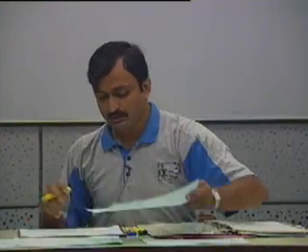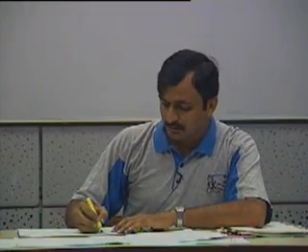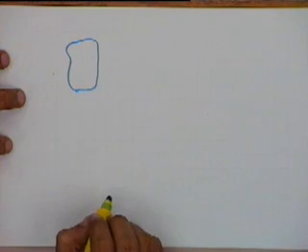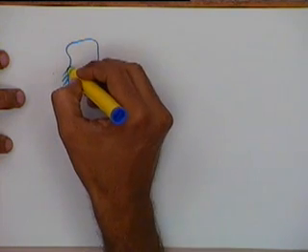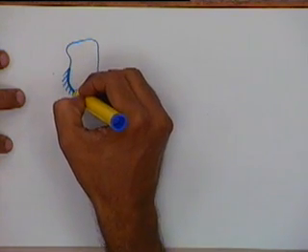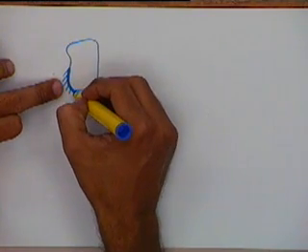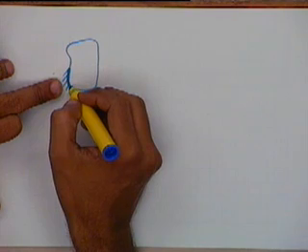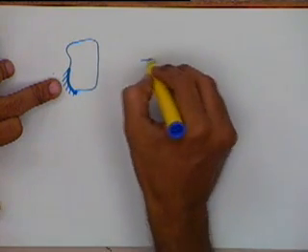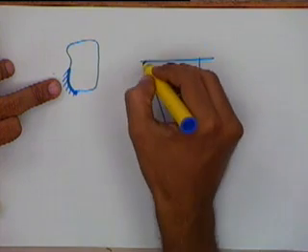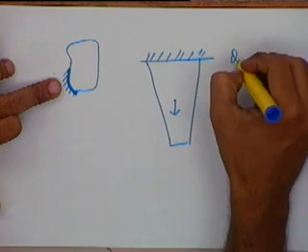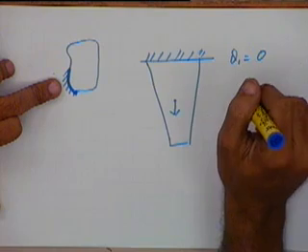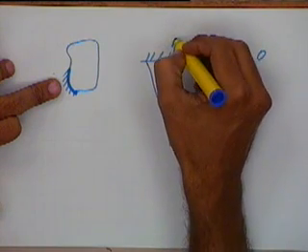But one thing that we have not seen so far is that, let us say we have a finite element problem with some boundary conditions. In order to constrain this body at this boundary, some forces have to be applied from the boundary. For instance, in the simple case, we mentioned that Q1 is equal to 0. But in order to get Q1 equal to 0, there will be some reaction from here.